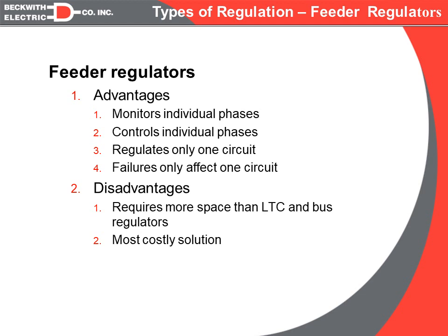A disadvantage is cost, obviously, and also space. But another advantage is now since we're regulating each circuit independently, we can have different voltage drops on each circuit and accommodate that without needing downline equipment.